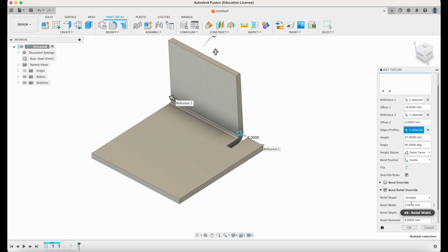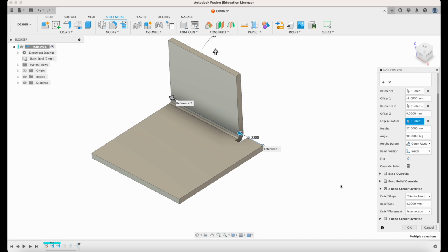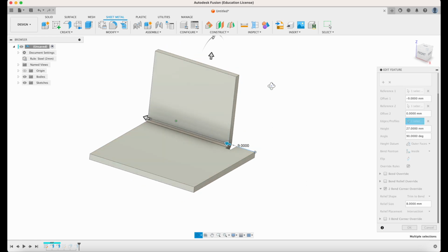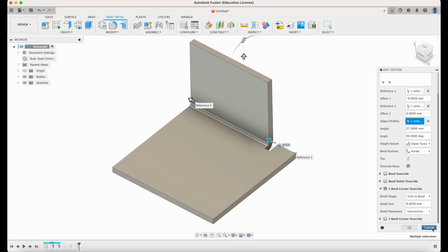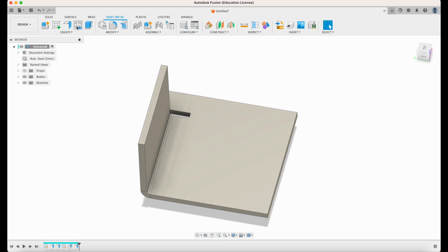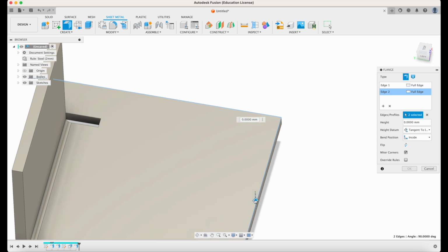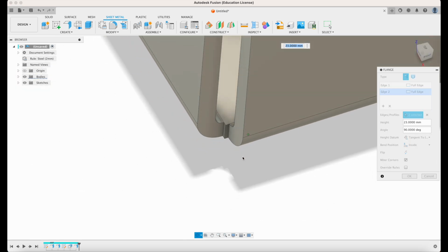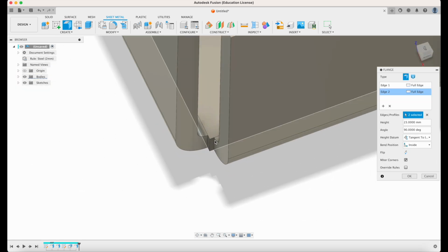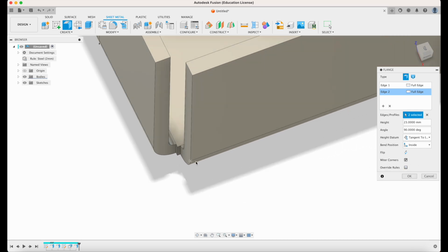So that's the bend relief. Now, 2 bend corner. From this point on, the options only work with multiple bends on sides. What that means is I have to create a new flange on this side, for example, with these 2 edges. So I have 2 bends that meet. And you can see I have this small piece, right? That's because I didn't control my overrides yet.